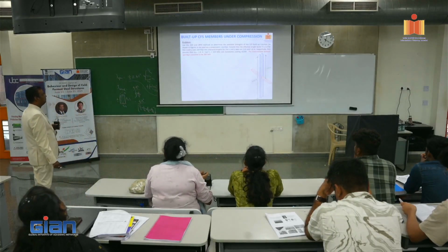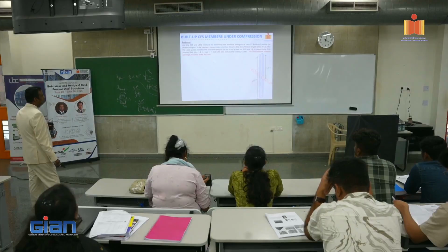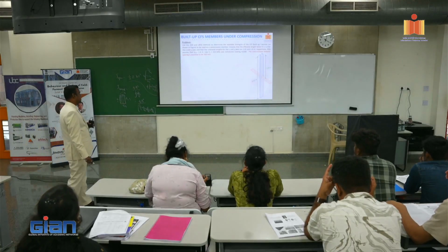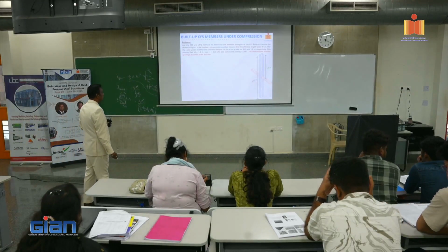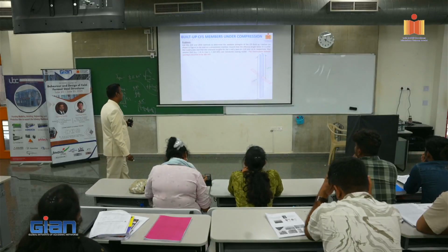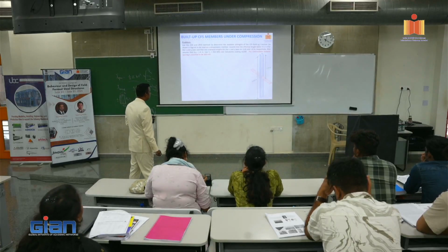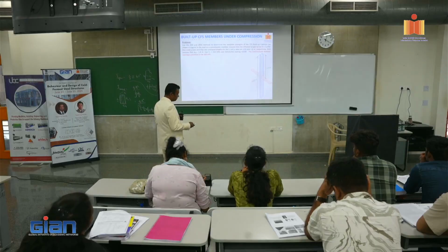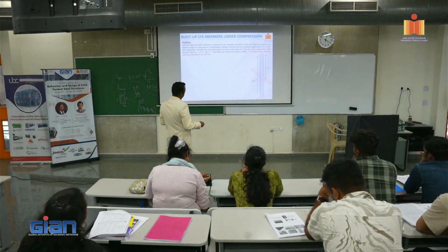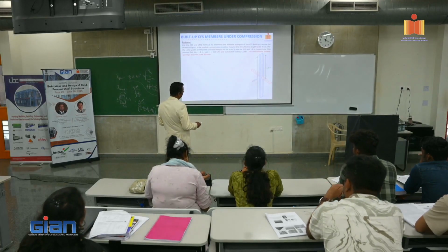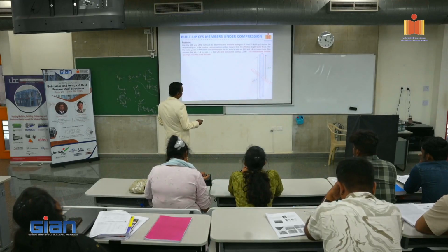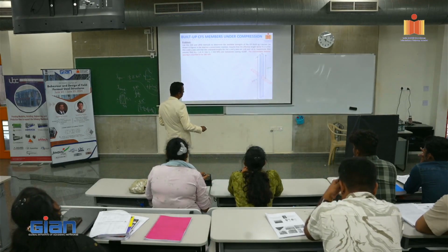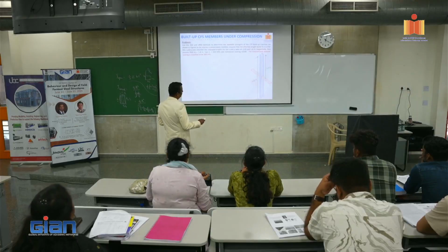Assume that the effective length factor K is 1.0 for x-axis and y-axis, and that the unbraced lengths of x and y-axis are 3.65 and 1.8 respectively. Right, so one side it is going to be 3.65 and another side it is going to be 1.8. You see this one, when it buckles like this, right, or it buckles like this.